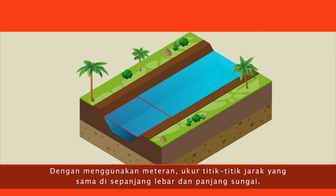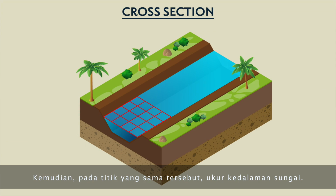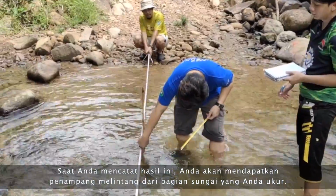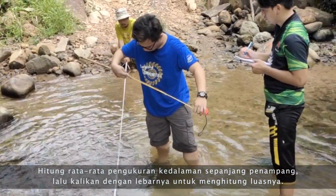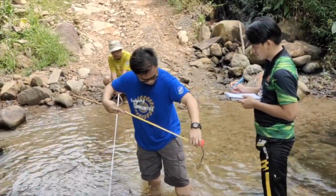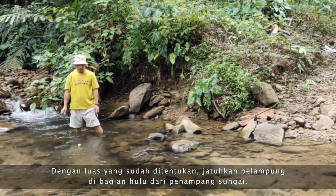Using the tape measure, measure out equidistant points along the width and length of the river. Then, at those same points, measure the depth of the river. When you take note of these results, you end up with a cross-section of the portion of river you are measuring. Calculate the average of the depth measurements along the cross-section, then multiply that by the width to calculate the area. With the area determined, drop the float in the upstream portion of the river cross-section.